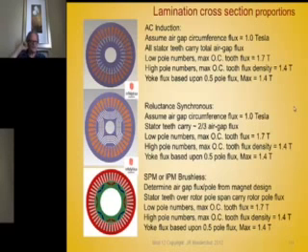So the total flux is less, since it is split between the two sides. And since the mass of the stator yoke is usually higher than the mass of the teeth, one would allow the tooth flux density to be a bit higher than the yoke flux density.